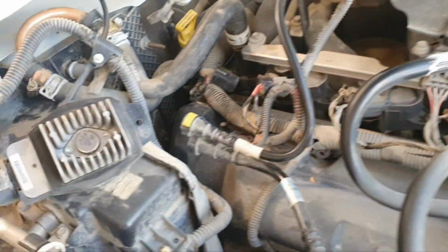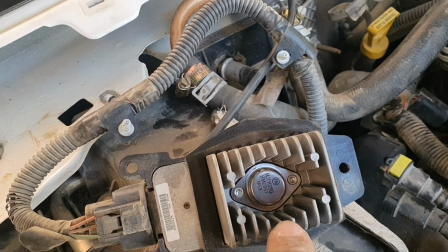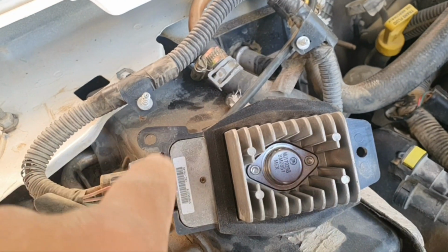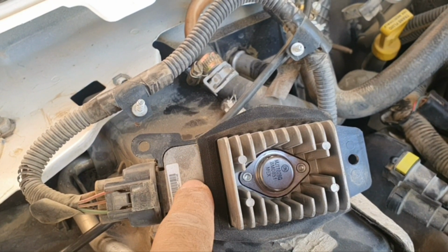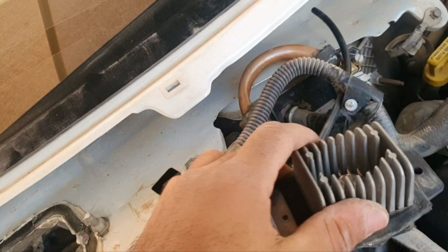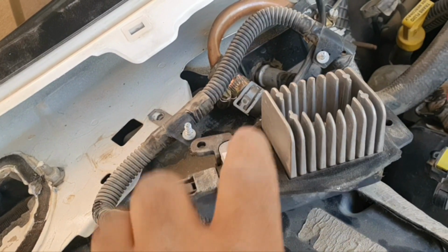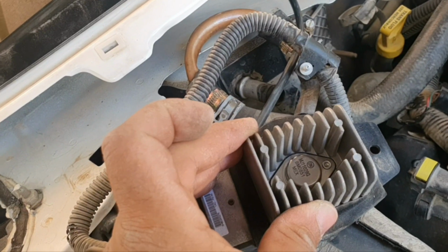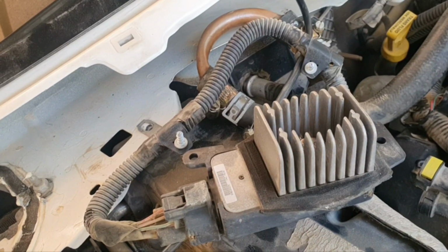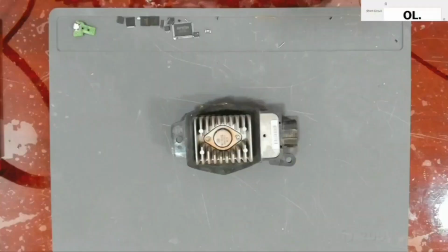Okay, so as you can see, this speed controller contains a heatsink and a transistor inside. Okay, and I think there is more circuitry inside this if we undo these 2 screws. Okay, so I will take it apart and see if I can fix it. Maybe this transistor is faulty, it's short circuit, causing the fan to go at high speed all the time. Okay, so let's see if we can fix this.